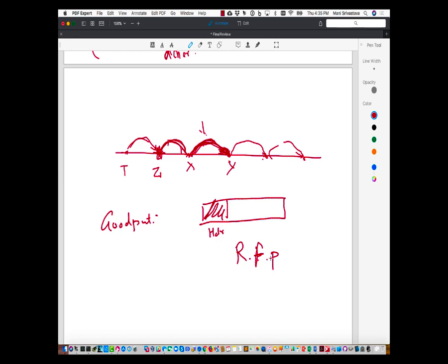One thing to bear in mind is that the way these packets work, you lose the whole packet. Usually these packets use some sort of error correcting code, and that code typically would have some limits, like maybe it can correct for a couple of bits. So when bad things happen, even if 1 or 2 bits are off, the whole packet is discarded.